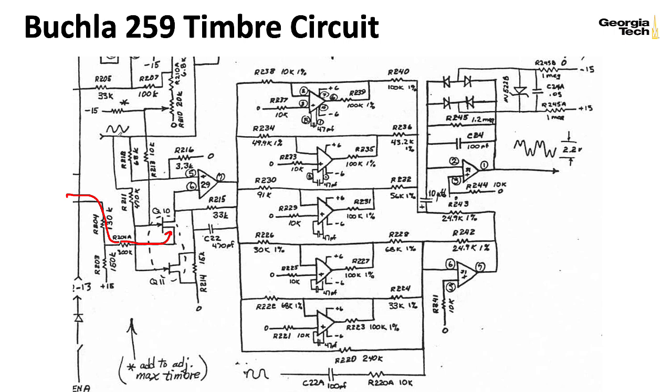Now, notice it's coming in through here. Again, part of the sinusoid is being applied to the base, I think to try to smooth out some of the weirdnesses of using a JFET in this mode. Notice it's also sort of being amplitude controlled by the timbre control itself. So the timbre control is affecting both the overall gain that we're getting from this amplifier, and the timbre control is also influencing how much of the symmetry is actually giving this little DC offset one way or another.